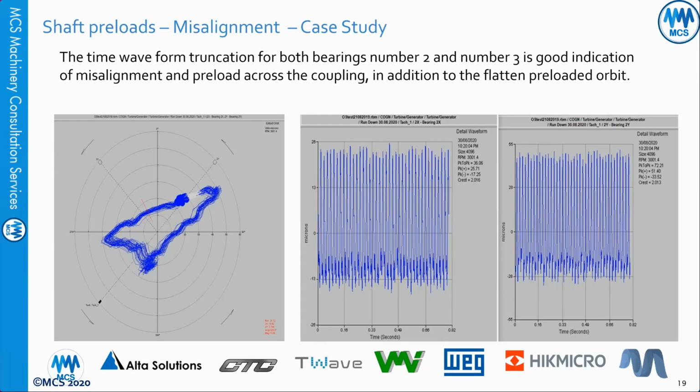So the unbalance itself, if this is your question, is some sort of preload. It can be considered some sort of preload. I don't say it's a good preload, but it's within limitation. If you have too much unbalance, you have very high vibration. But the unbalance is some energy, some sort of preload on the shaft, to avoid the shaft running in the middle.